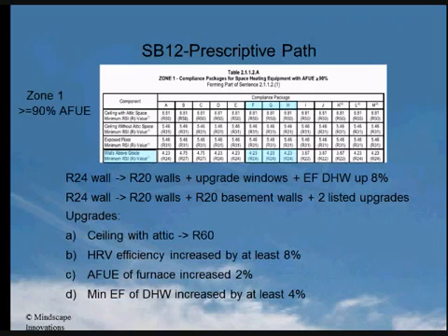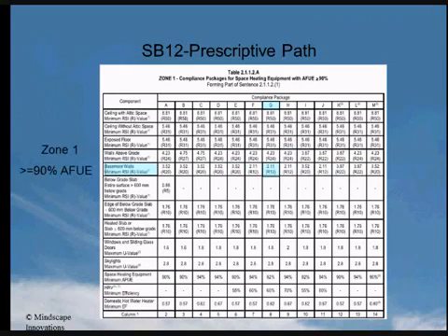Basement walls must be a minimum of R12 insulated to within 200 millimeters of the floor slab. For walkout basements, the wall containing the door, and any wall where over 50% of the wall area is above grade must meet the walls above grade insulation requirements. In package G, that would be R24.